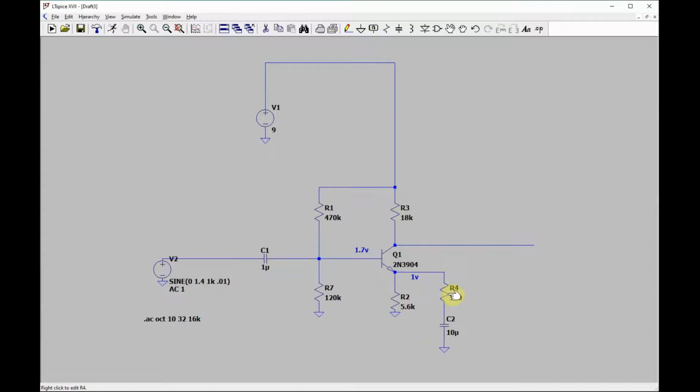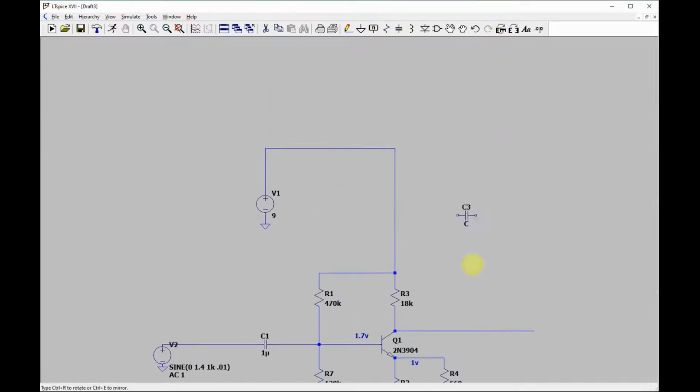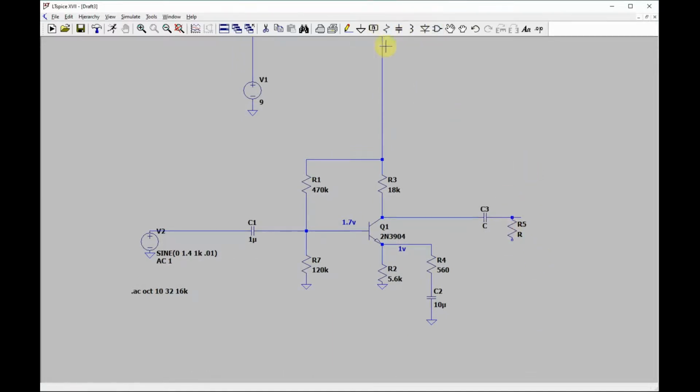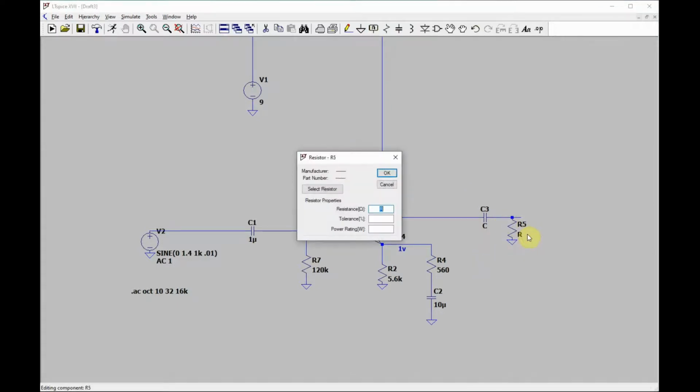Now, this will blow this out of the water, because you're going to clip, because we're just about clipping and running maximum now. So you might use that if you said, oh goodness, I thought I was supposed to have a 2-volt signal. I only have a 200 millivolt signal. I have to redo all this. No.